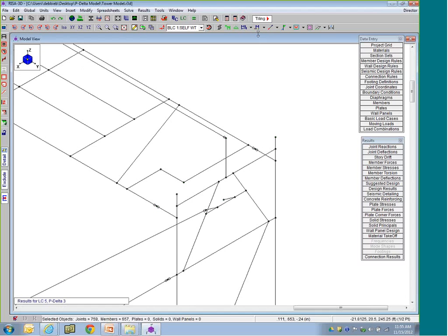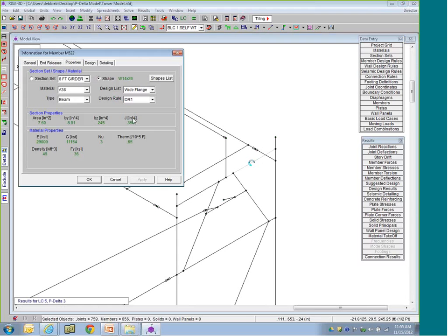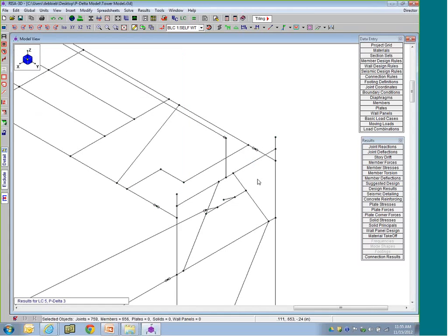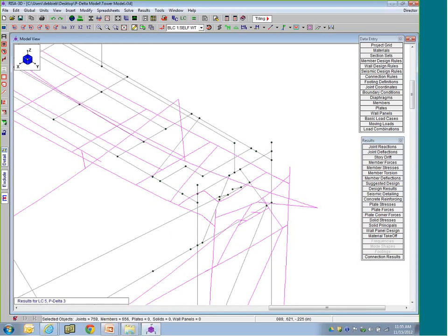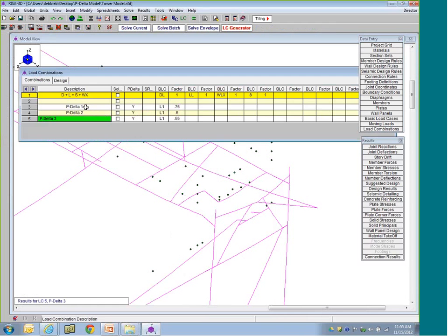And so you might go ahead and change this to an HSS shape that has a bigger J value, or torsional constant, because this one's pretty low, so it can't resist that torsion. But if you had something stiffer there, then you might be able to see that work a little bit better to resist that so that frame doesn't start to fly off the screen. So this method walks you through taking each load combination and bringing it down slowly until you can get it to converge.